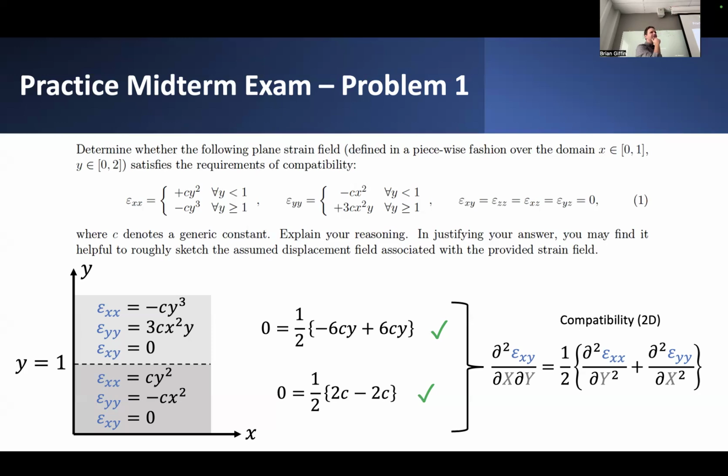Say again? Yes, the displacement field has to be continuous. That's a requirement for compatibility. If the body is originally an interconnected domain with material points that are connected to each other before the whole thing starts deforming, then after this body deforms, assuming that no fracture happens, there's no splitting apart of the material. In that circumstance, we also say that the resulting displacement field should be continuous. And that's necessary for the body to remain compatible or continuous after deformation.